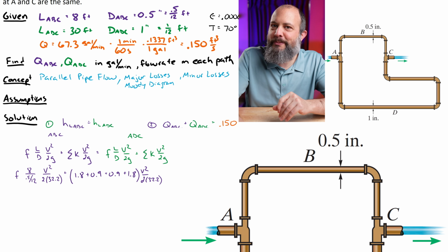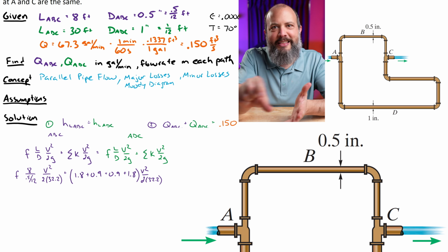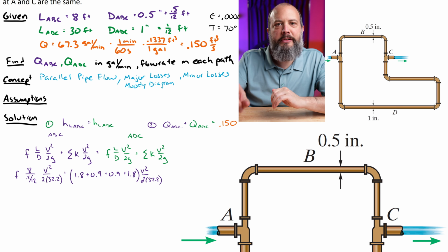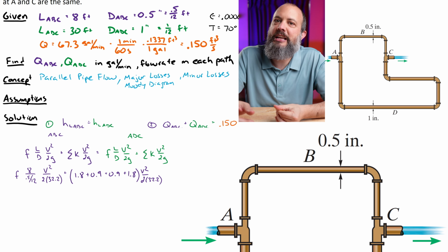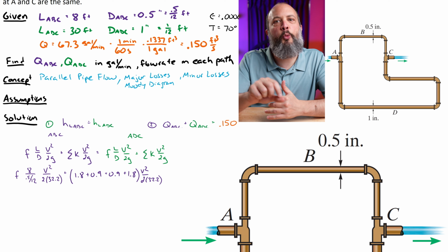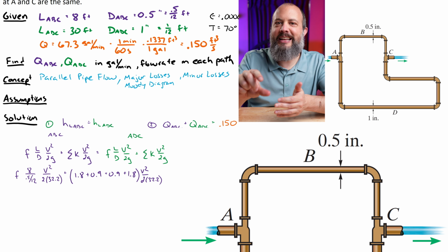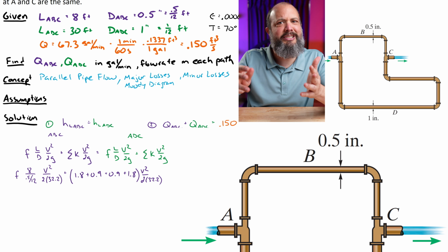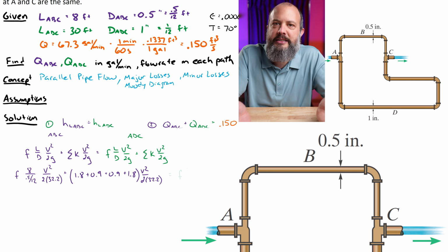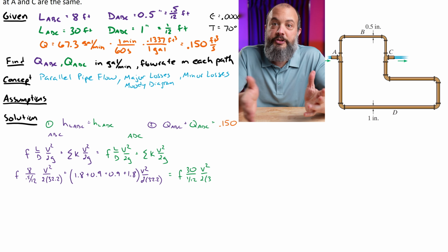If I wanted to make an assumption and choose a value a little bit higher, like 2.5, I could just write in there why I'm justifying that use. So I think either option would be okay here. One, choose the best number you have, which in this case would be 1.8. Or write a brief comment as to why you're using a different number. So I might use 2.5 and say 1.8 plus a little bit extra to account for the sudden contraction inside the T-joint.